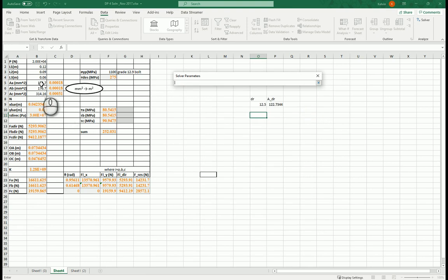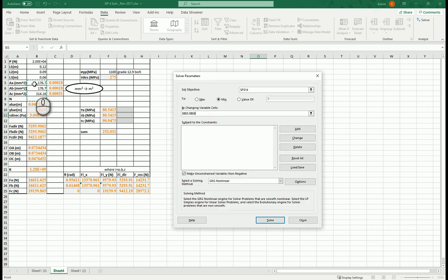So we'll be changing the shear area, so you could drag from 5 straight down to 8, hit enter. So we'll be changing the shear area of bolt A, B, C, and also the factor of safety. Because we have it as 2 right now, but we could come down to 1.5, we could come down to 1.1. Once we're greater than 1, we know that we are in the over-design sense. If we are less than 1, it means that we will be failing. So we want to ensure that n is greater than 1 at least. 2 might be a little too high. Both sizes might be too big.